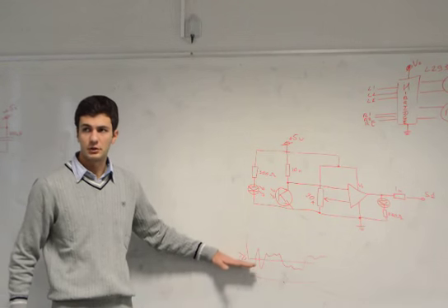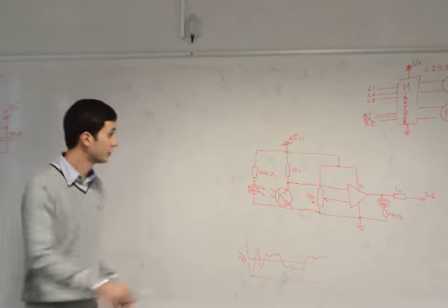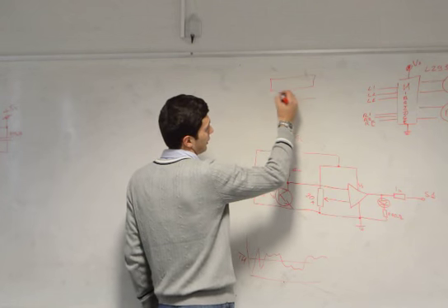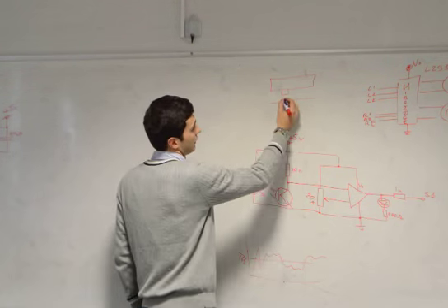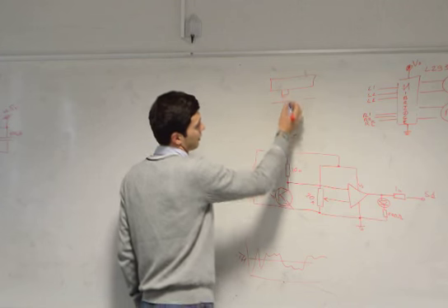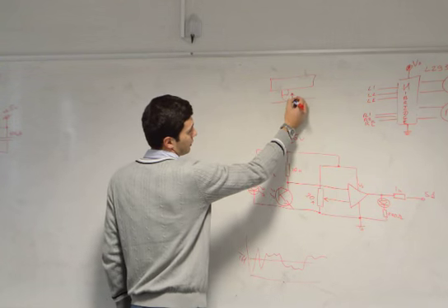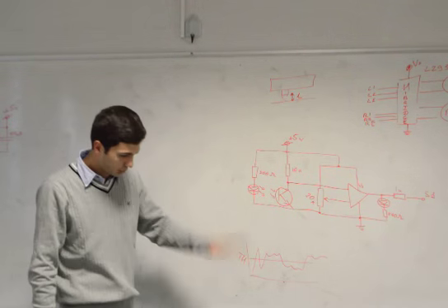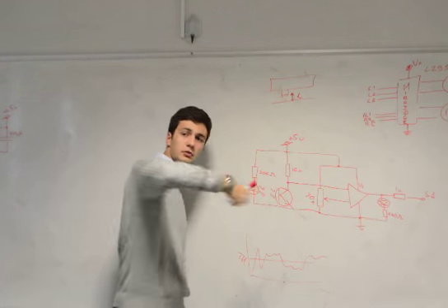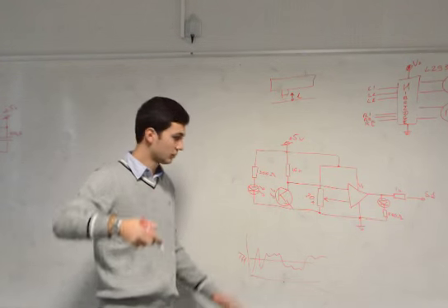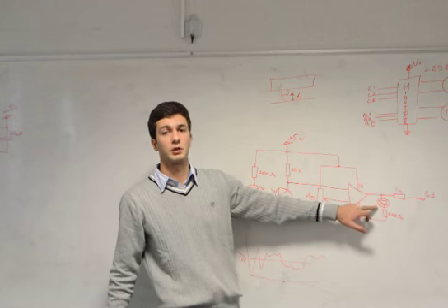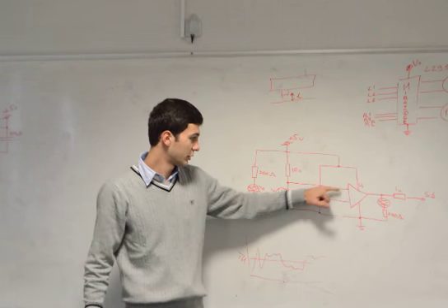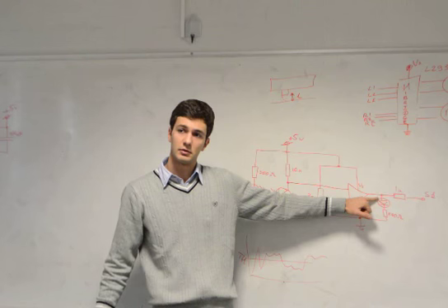We should set the threshold in a way that works from the distance that we want. For example, this is the robot. This is the sensor. We have the light coming down and going back up. This is the distance between the sensor and the ground. So we put the robot on the ground and set this threshold to give us the right reading. And with this LED, we can see if it's white or black. Is this part clear? Because if this point goes more than this, the LED lights.